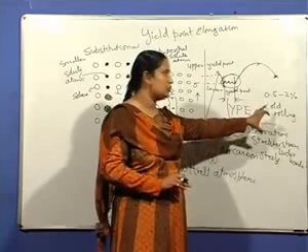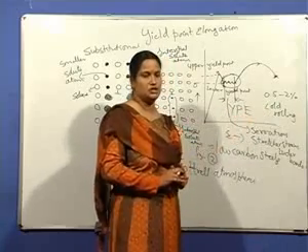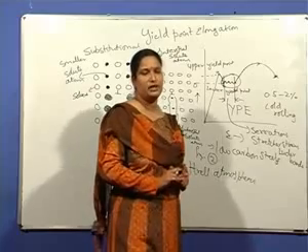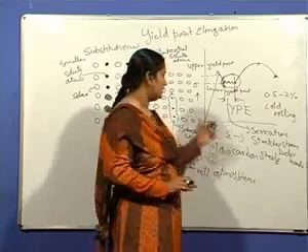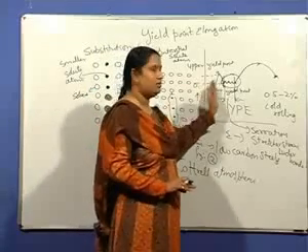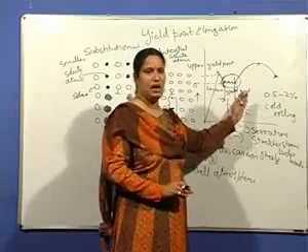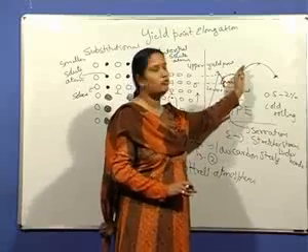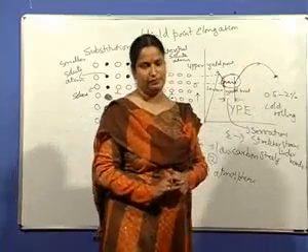Because of this small amount of cold reduction, the dislocations are completely torn away from the atmospheres, and the stress strain curve follows the normal curve.